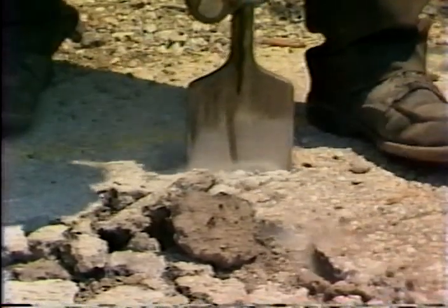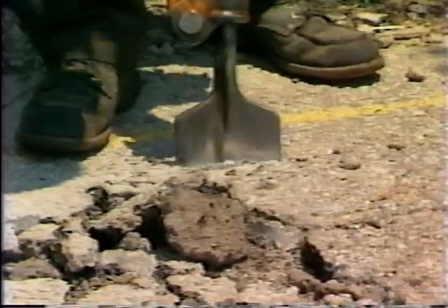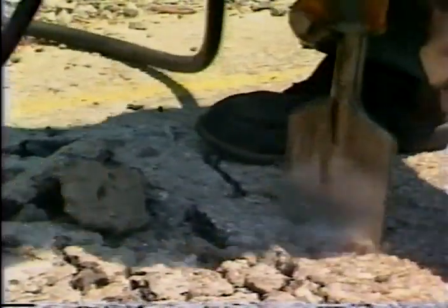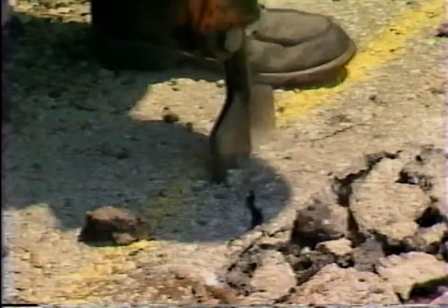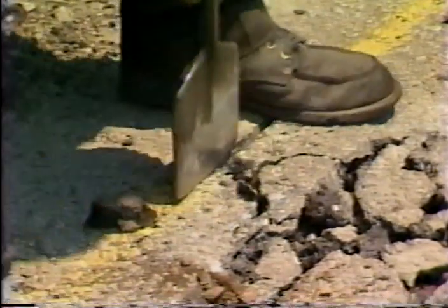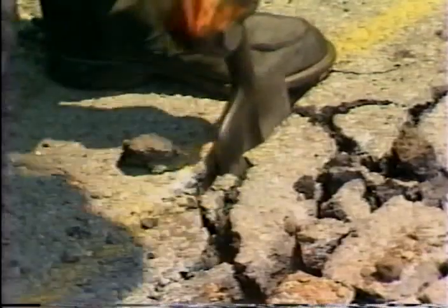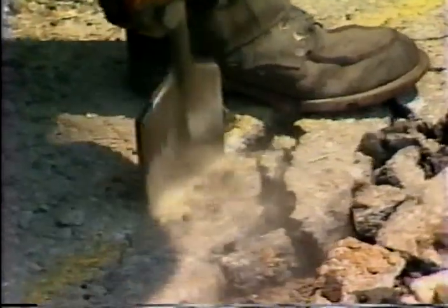Cutting depth is also important. Cutting continues to a depth where good pavement or base material exists. Make the final cut along the marked edges of the patch area, thus providing a vertical face around the edge of the patch area. A pavement saw may also be used to remove the distress area instead of a jackhammer or other pavement cutter.